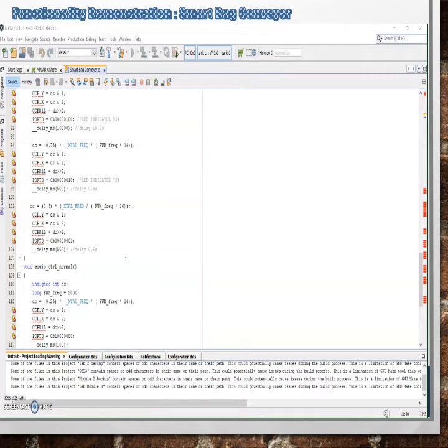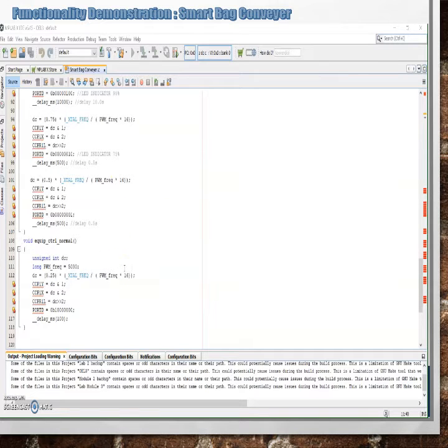Running at 95%, it will run for 10 seconds if there is no detection. If a bag is detected, it will continue at 95%. If not detected, the program will decrease the motor speed to 75%, 50%, and our normal condition.